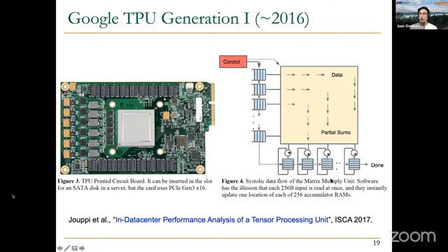And what the systolic array basically does is perform a matrix multiplication, multiplying and accumulating in these accumulators here at the output. Why matrix multiplication? Because matrix multiplication is a key primitive for neural networks and many machine learning and artificial intelligence algorithms. We are going to talk about matrix multiplication in detail in this course and about how to lower convolutions into matrix multiplications, which is a very common technique in training and inference of neural networks these days. And this is why this operation is so important and why there are units and entire accelerators specialized for this specific operation.